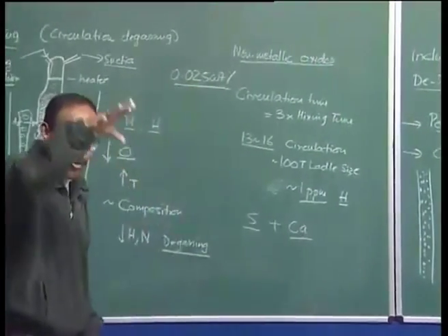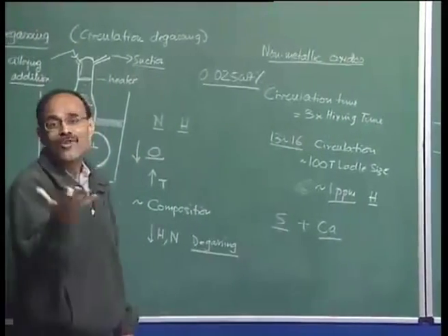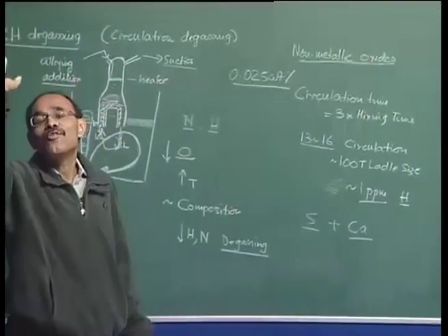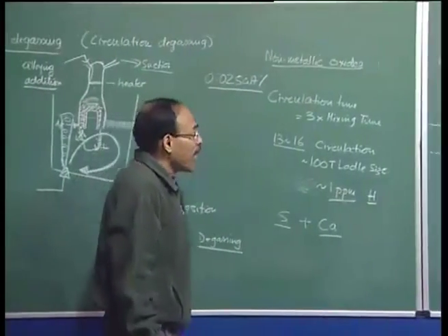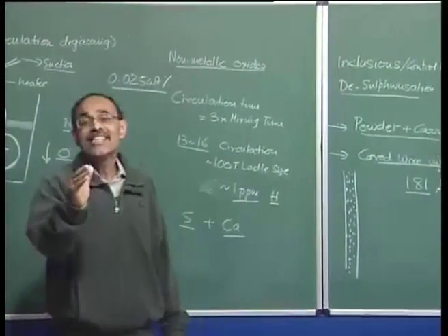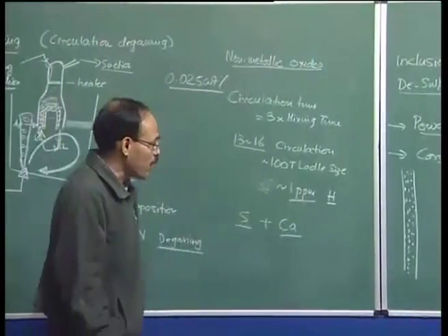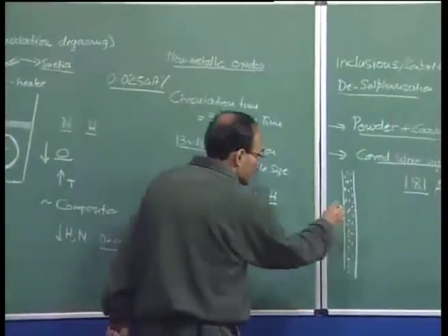A lot of the calcium that we are going to inject into the melt does not actually do any useful work; rather, it is going to escape to the surroundings. So this is a very important point, and that's why calcium treated steels are extremely expensive.